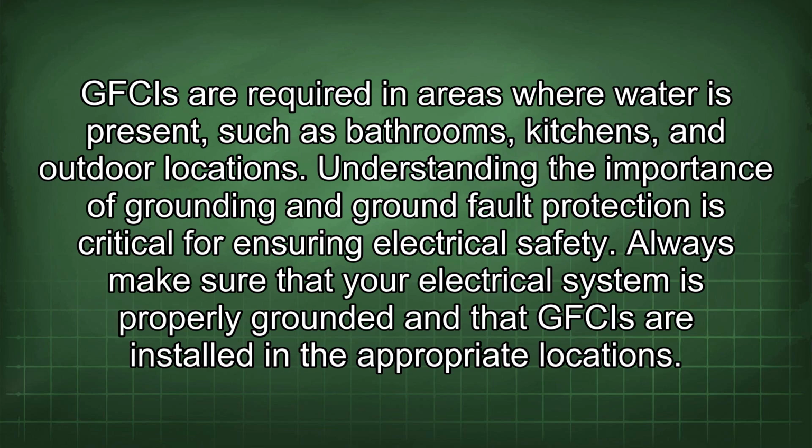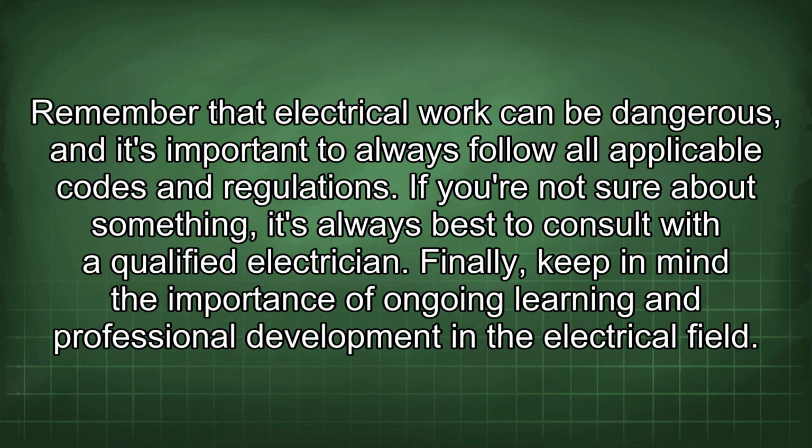Understanding the importance of grounding and ground fault protection is critical for ensuring electrical safety. Always make sure that your electrical system is properly grounded and that GFCIs are installed in the appropriate locations. Remember that electrical work can be dangerous, and it's important to always follow all applicable codes and regulations. If you're not sure about something, it's always best to consult with a qualified electrician.